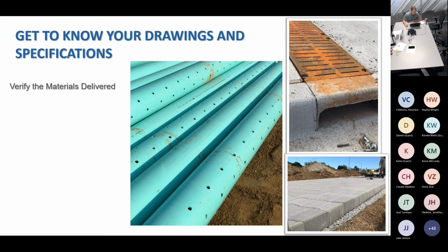Get to know your drawings and specifications. When you're out in the field, especially with green infrastructure projects, but all projects as well, just make sure that the materials that are delivered to the site are those that have been approved through the submittal process. Whether that's underdrain pipe, BMP soil, I mean, there's just all kinds of materials that it's very important for the functionality of the green infrastructure project. They are the correct materials.